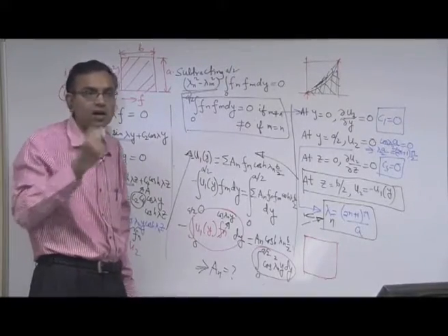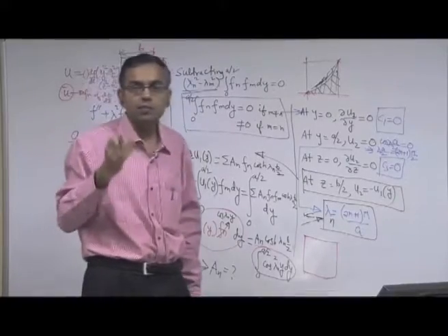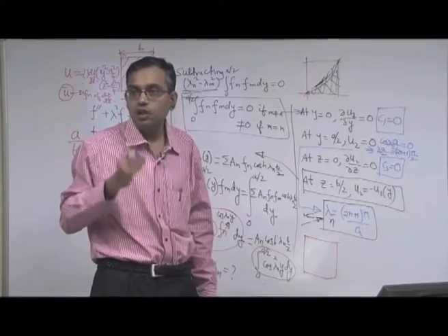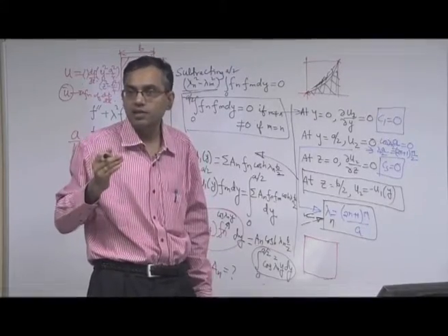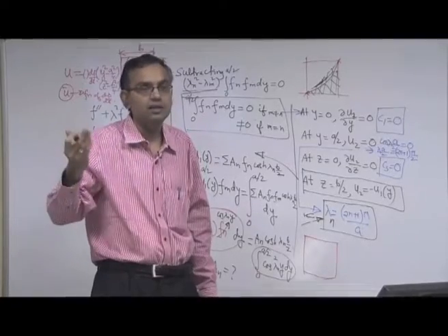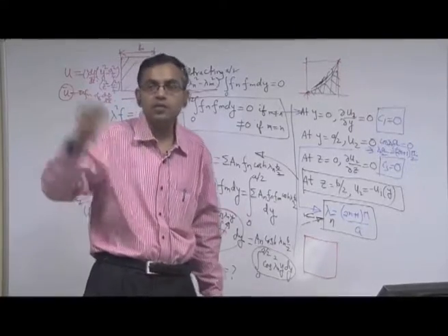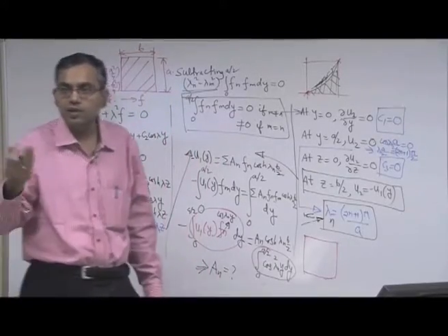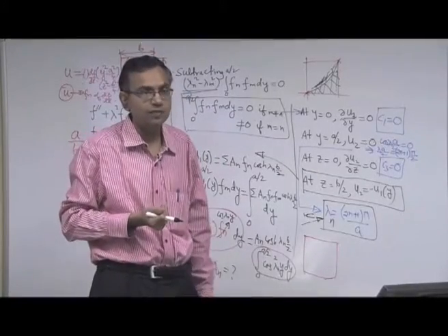This is very analogous to analysis in the boundary layer theory. In the boundary layer momentum integral method we use approximate velocity profiles, and many approximate velocity profiles are widely different. I mean, some are linear, some are quadratic, some are cubic, some are sinusoidal. You have worked out these problems in basic fluid mechanics.